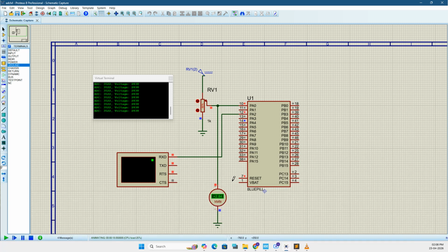Using this you can also measure AC voltage, but instead of a pot you have to use a precise, proper voltage divider. There is not a much more complex circuit in your multimeters. If you open your multimeter, you can see the voltage dividers are there. So this is your voltmeter based on your STM32.